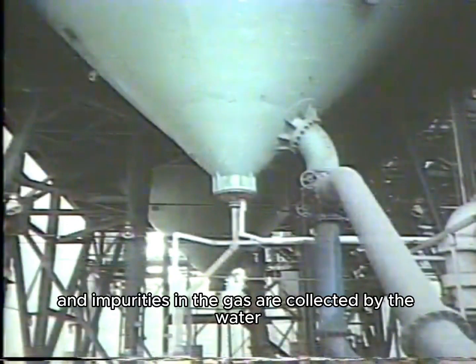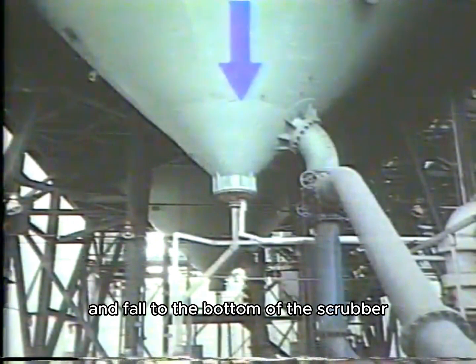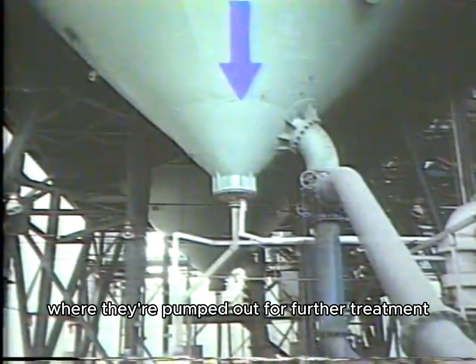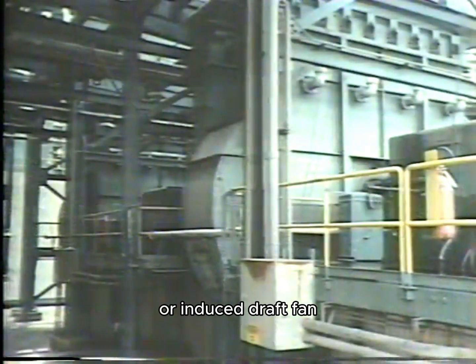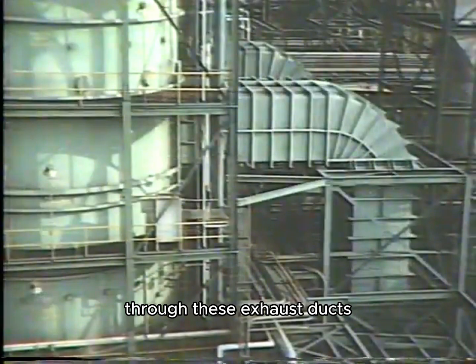Many of the particles and impurities in the gas are collected by the water and fall to the bottom of the scrubber, where they're pumped out for further treatment. The cleaned gases are pulled out of the scrubber by an ID, or induced draft fan, through these exhaust ducts, and are vented to a stack, where it's released to the atmosphere.